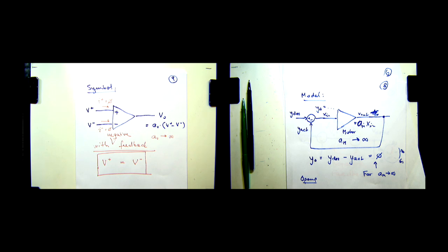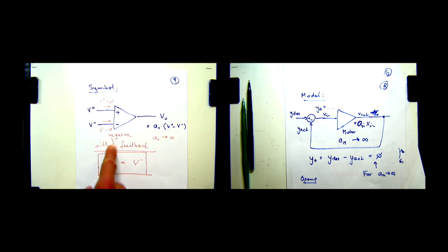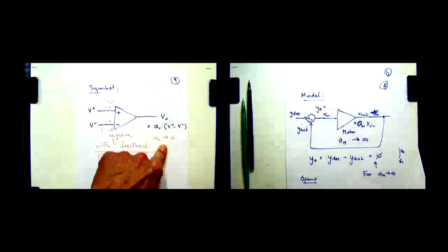So the assumptions are that the gain is infinite and that we have negative feedback. We did everything right. We will make big use of this, not only for calculations. It's just like when you're driving on the road, your cruise control makes it that you go at the speed that you tell it to. For that it needs an infinitely powerful motor. In cars you can get that, and they are gas guzzlers. With op-amps, it's a lot easier. You just buy a run-of-the-mill model, and the gain is like 1 million, and that's good enough. The error is negligible.